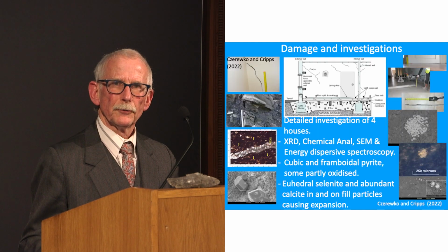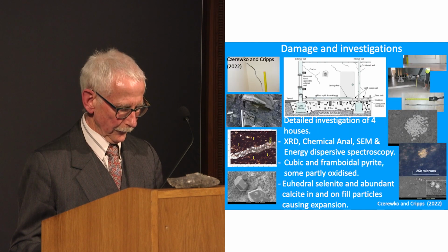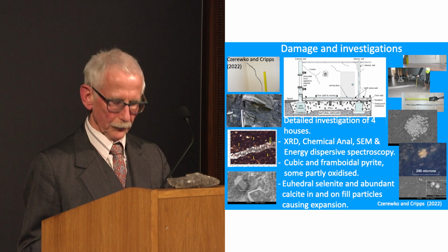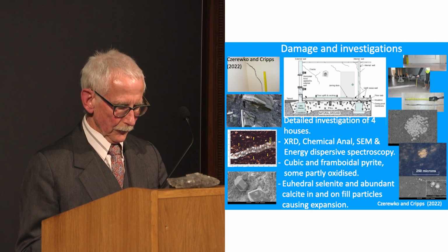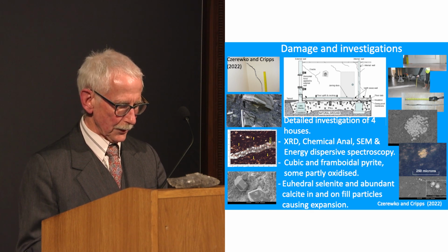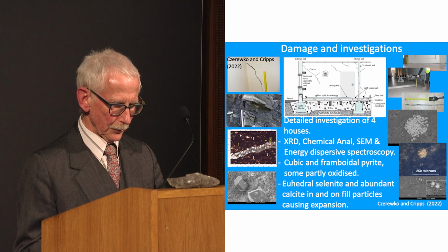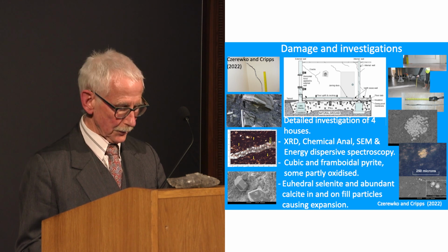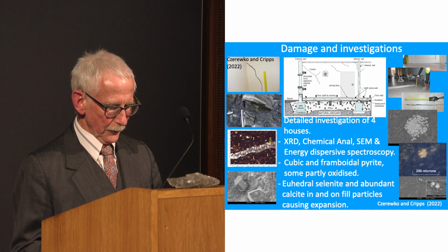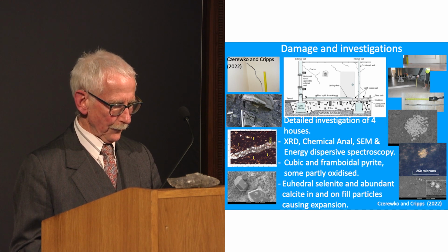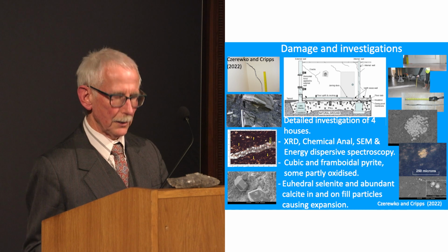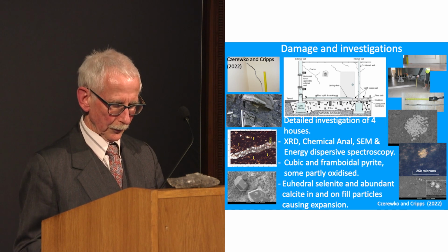This shows the nature of construction, with a fill below the floor slab, an expansion of the floor slab leading to the cracking of walls, heave and cracking of the floor slab, sticking doors, and in one case the loss of spindles from a staircase banister. Four houses were investigated in detail with sampling, mineralogical and chemical testing and scanning electron microscopy work.